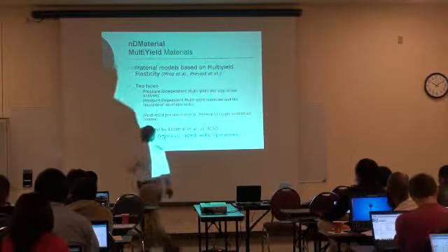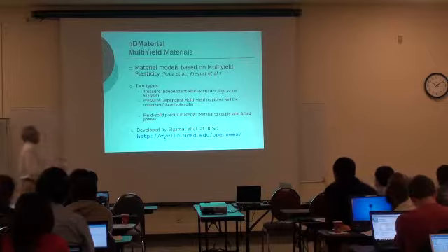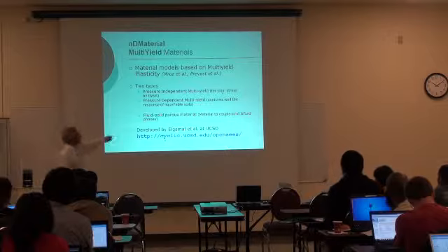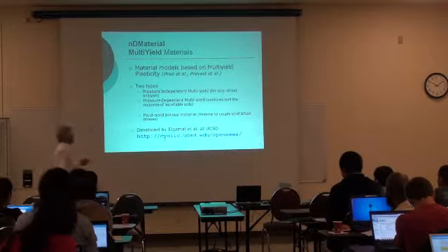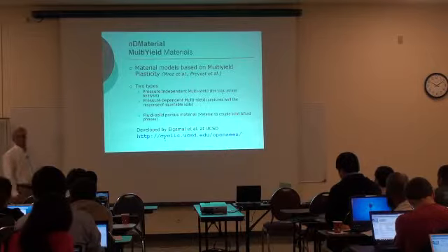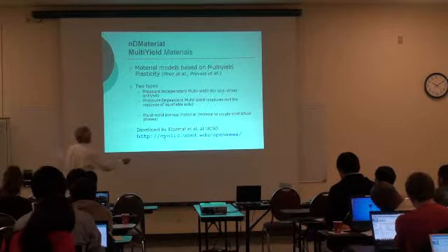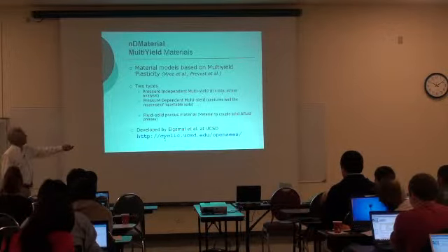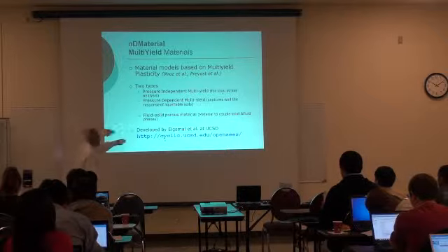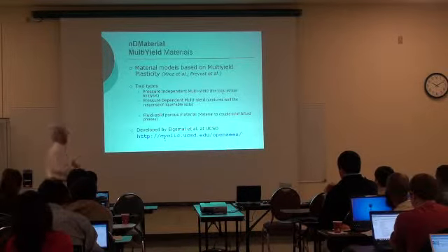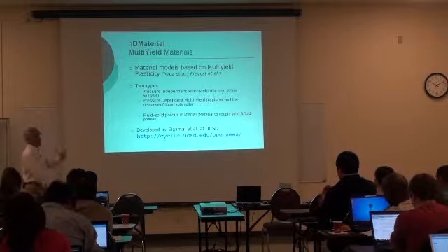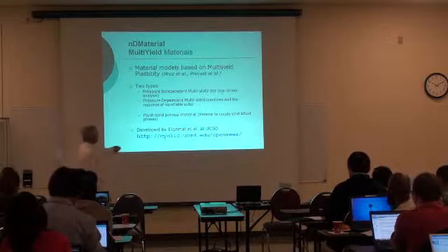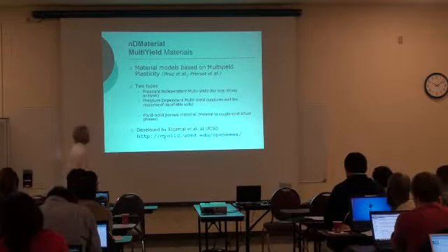So the multi-yield plasticity models were initially established by Ross et al., and then they were made popular by Prevost and others. So in OpenSees, there are two types. One is the pressure-independent multi-yield model that is commonly used for total stress analysis. And then you also have the pressure-dependent multi-yield that captures well the response of the soil under earthquake excitation, and also, in this particular scenario, captures pretty well the response of the soil when it liquefies.